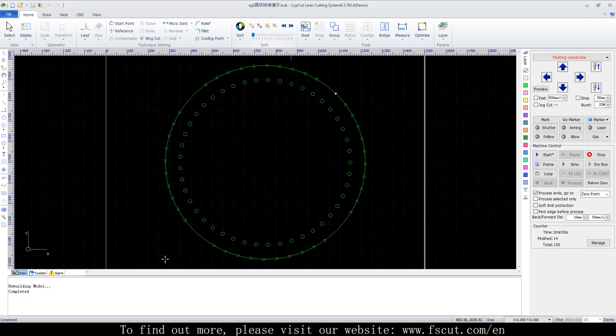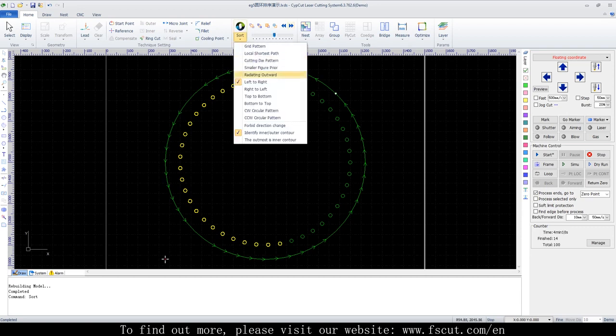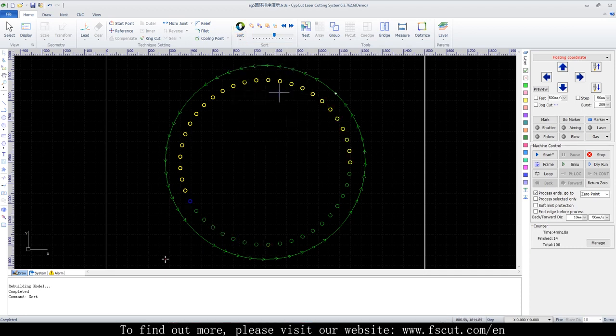As we can tell, if we use these four modes for annulus, this is inefficient. But radiating outward, clockwise and counterclockwise are just perfect for annulus patterns. This way we can skip over unnecessary travel paths and hence improve efficiency. And here we've got 3 other options to be chosen as needed.